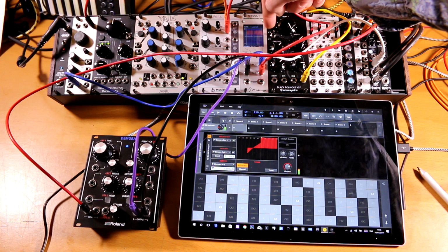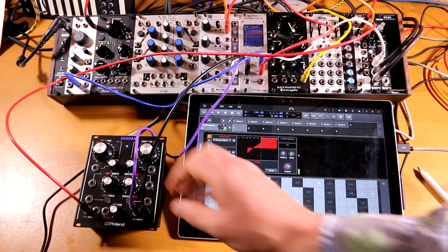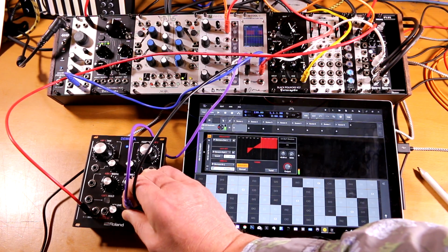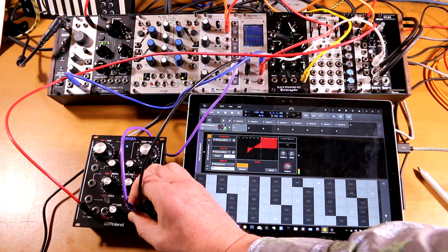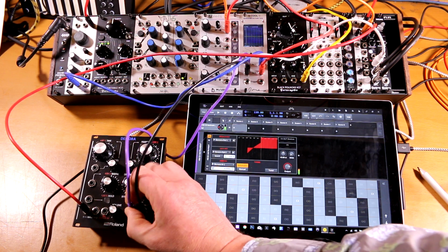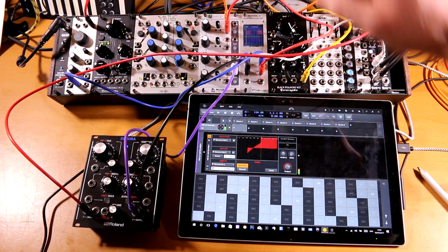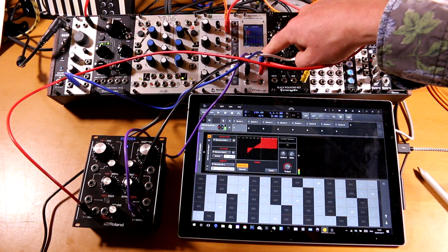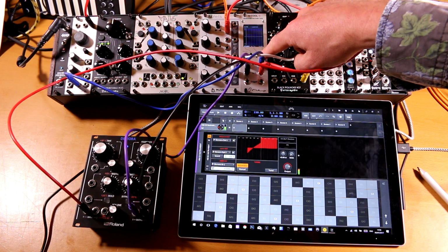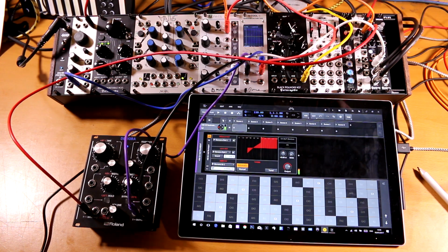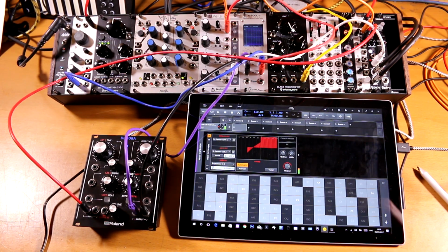So I don't know if you can see here, we have on the pitch output, it's not a steady line, it's very much a wavy line. But if I pan that up, if I do something with that, can I make it look more like a sine wave? Yes, I can, look. So that's actually what we're getting on that output, not a steady CV that we want.